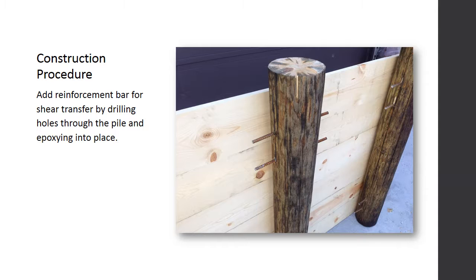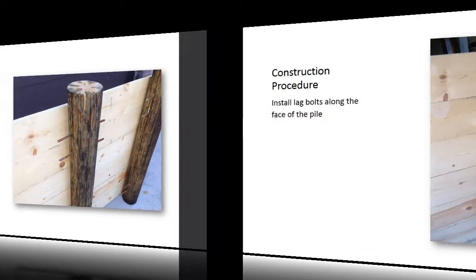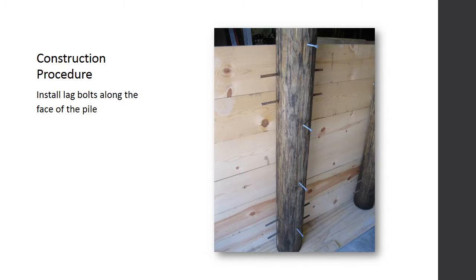Add reinforcement bars for shear transfer by drilling holes through the pile and epoxying into place. Install lag bolts along the face of the pile to serve as standoffs for the reinforcement bars that span from pile to pile.